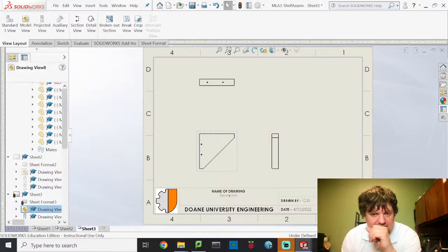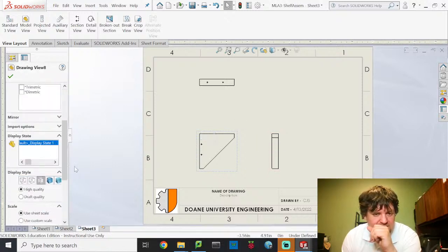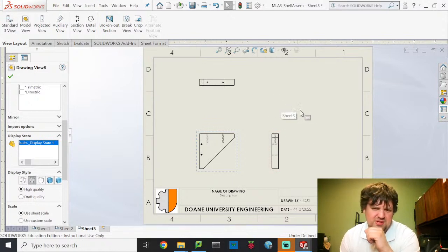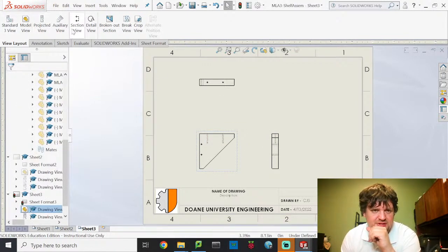Now actually what I am going to do quickly here on this one, because it's kind of a smaller part, this piece needs to show the hidden lines. And when you do that, it shows the locations of where everything is relative to each other. That can be really helpful for positioning, and certainly here for showing the depth. Because all of those lines are now dimensionable.